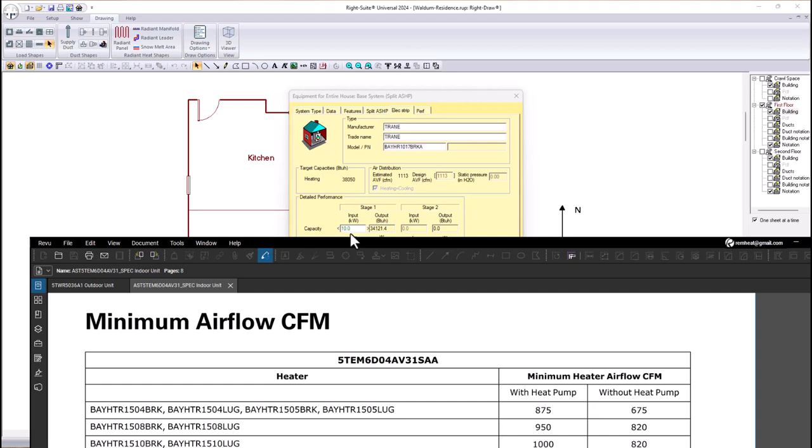The central, which is going to be Virginia in the middle of the US. If you're going to the north, the central, 10 kilowatts is a good idea. 10 kilowatts, 15 kilowatts, you name it. In the north, especially for a 3-ton unit, you're going to have at least 15 kilowatts, because it's colder.